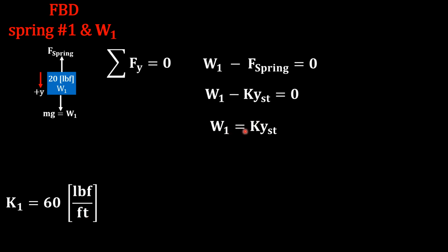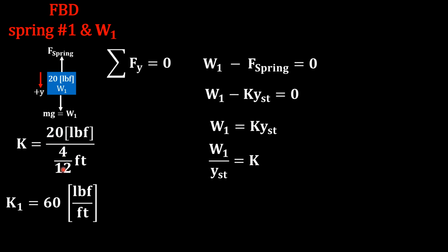So weight 1 is equal to K times y stretch. Weight 1, y stretch equal to K. So K is 20-pound force divided by 4 over 12 to convert inches to feet. And we got 60-pound force per foot.